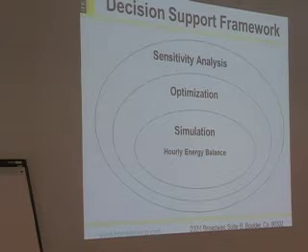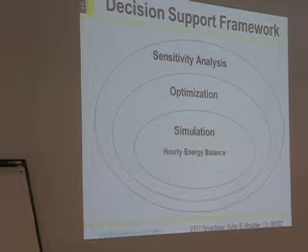You simulate many different systems under the same conditions and rank them by life cycle cost or net present cost. That's the optimization layer. So it tells you what's best, but it also lets you look at the full range of different systems and how they compare and how much better really is it, et cetera. So we do the energy balance for one time step, then we do it for many time steps, and that's a simulation, and then we do that many times over and compare them.